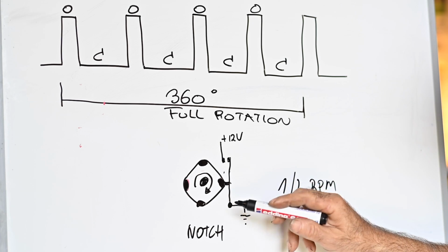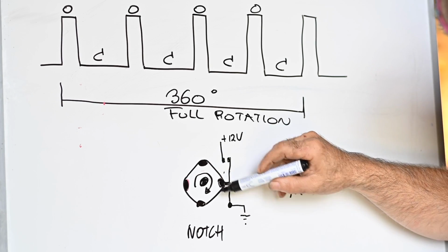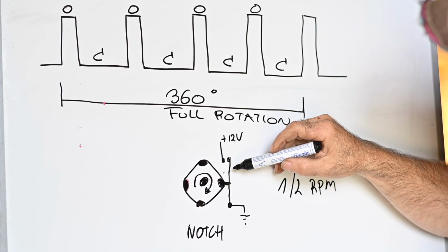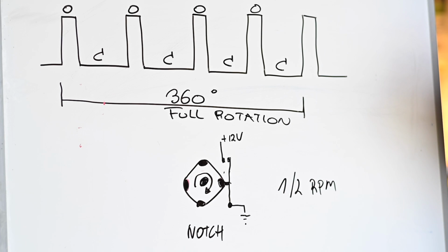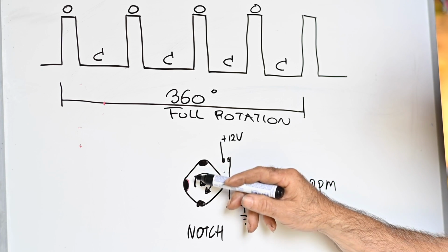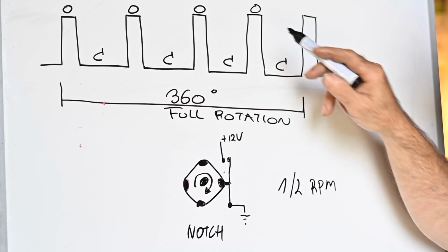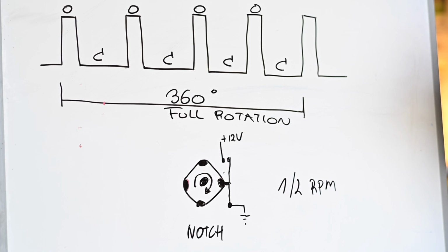So this is rotating, and while this is rotating, it's going to open up these points on the notch areas, and it's going to let the contact breaker points close whenever the notch has passed this little lever point here. So we can say that for a full 360-degree rotation, we will have 4 times an opening of the breaker points. And that's what I show here. O stands for open and C stands for closed.